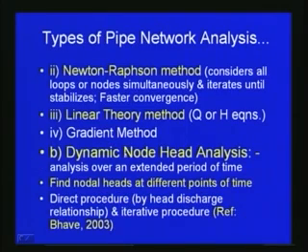And then the second type of analysis which we want to discuss briefly here is dynamic node head analysis. As I mentioned, in the dynamic node head analysis we will be looking for the heads at different points of time, so it is the analysis with respect to time. At various time levels or time intervals, we will be calculating the nodal heads at various nodes.